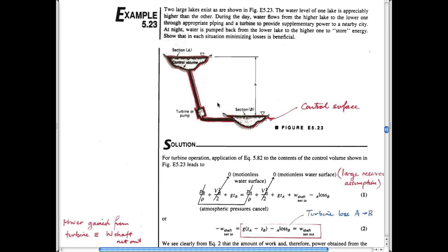So we showed the example of pump storage, and so this is just an example using exactly the same. Now we don't have to worry about changes in enthalpy within the system, so if that's the case, then we can write Bernoulli's expression that neglects that. We can write it in a variety of ways. I prefer to write it, although the question doesn't do it this way, I always just remember these things in terms of heads. Upstream and downstream, being equal to just the same amount downstream.